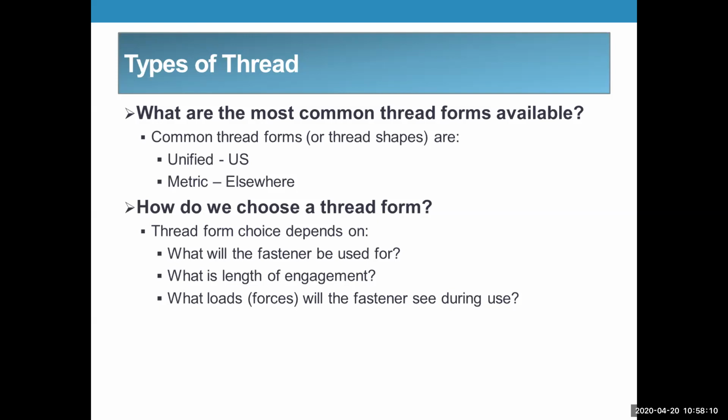When you think about it, if you're pushing down on the beam in the center and it's supported on each end, it's like a lever arm. So it's going to create a rotating load or moment load on each end where it's supported, that's going to add forces to those connections.